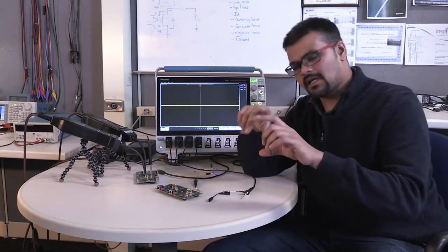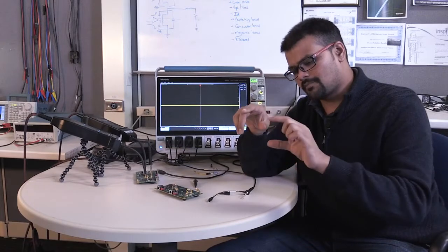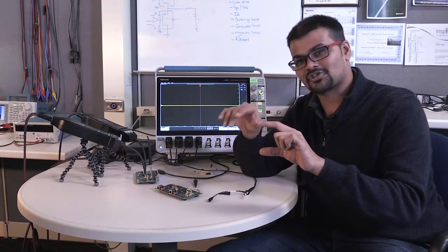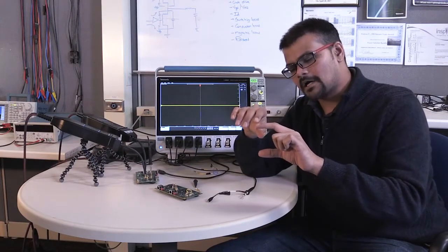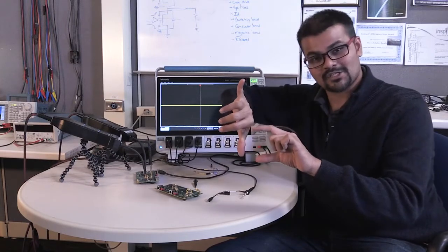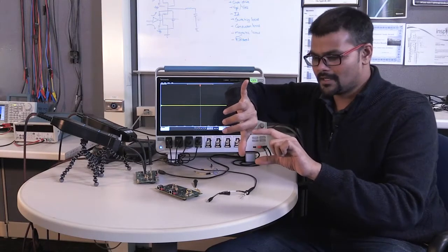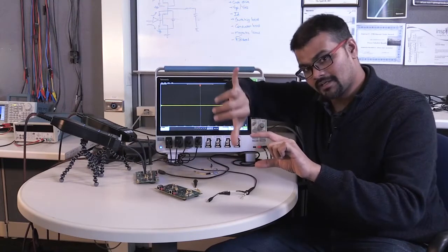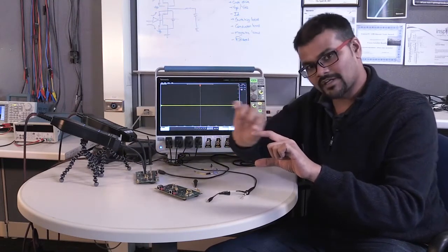The other piece of it is, think about the measurements we are trying to make, right? So we are trying to measure what's happening on VGS, we are trying to measure what's happening on the shunt, we are trying to measure the gate charge and so on in presence of a VDS measurement, which is 400 to 600 volts, right? So if you think about this problem, the vertical resolution you need has to be really high if you really want to see details on this, right?